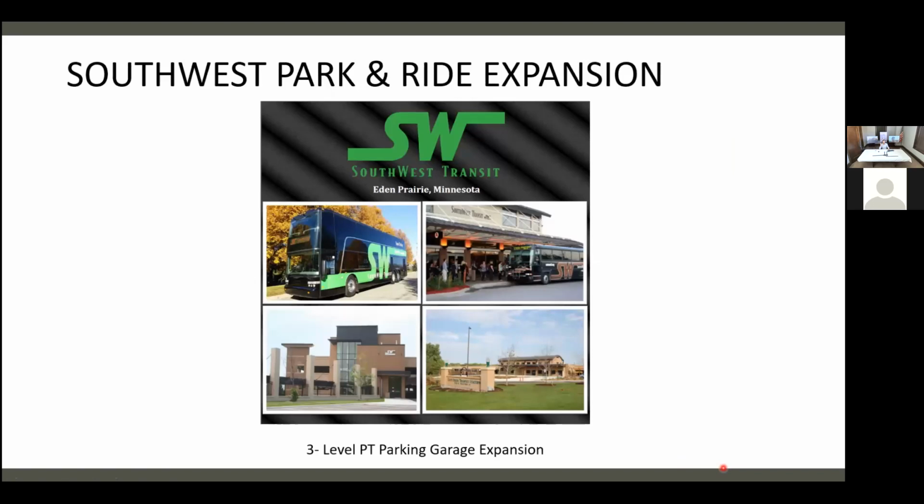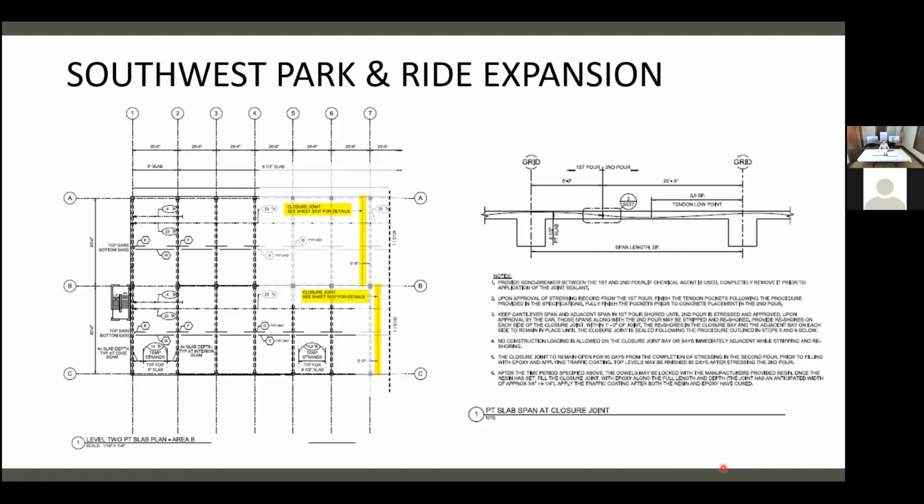This is a parking garage we had, a federal parking garage, 3-level PT. The lockable dowel was actually specified at this closure joint, which had the 5th point off the column, okay? They showed it. I think Kimley Horn was the engineer. They must have designed their lateral system to not transfer high tension loads in the diaphragm. It's not in a seismic area. So, if you're okay with epoxy being in your slab, the lockable dowel uses an epoxy grout that, if you have a fire rating, epoxy goes soft at like 150 to 200 degrees.